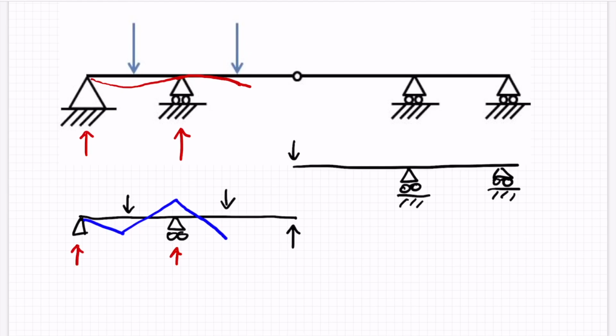That will go down until we hit this concentrated force, and that's going in the opposite direction. So okay, that's going to go back up, and we need to arrive at 0 by the time we get to there. So that should be arriving at 0 here. It arrives at 0 because that's a pin. So let's draw this part of the beam in first.